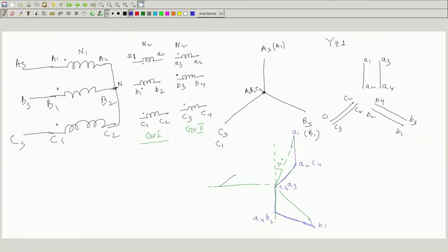and this can be broken up into these two phasors, this one parallel to B3, B4 and this is parallel to C3, C4, C1, C2, is not. Then based on this I come here and connect accordingly. For example, A1, A2 is connected to C4. So, take a piece of wire, connect it, and which three are shorted, A3, B3, C3, short them, is not.